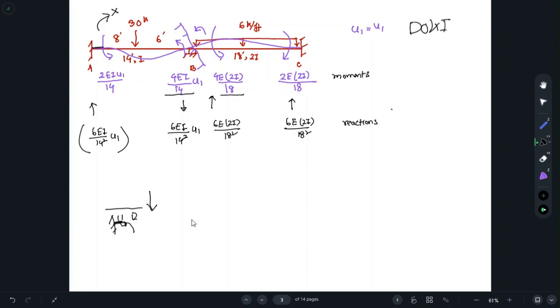So because of this, the loading creates a clockwise moment and the support creates an anti-clockwise moment. And for that, you can see up to these points, it is actually not deflected. Here is the same case. The loading creates a moment this way, and this is creating a moment this way. So I think there will remain no confusion regarding the sign of moments.